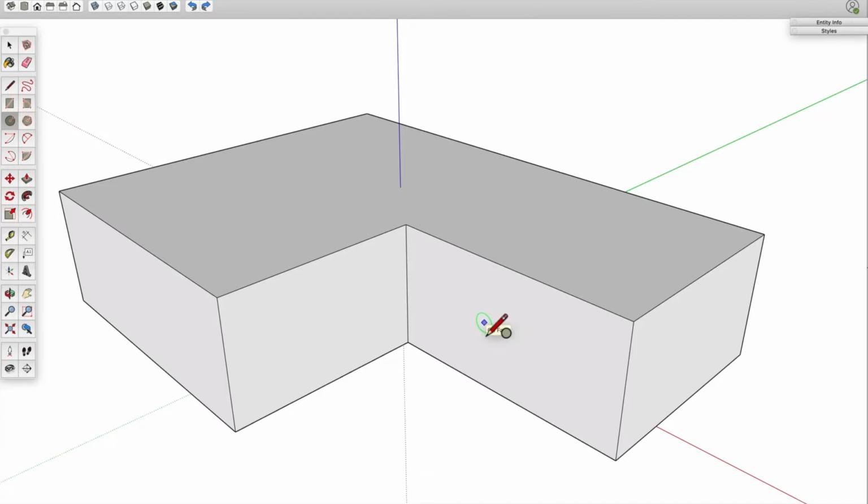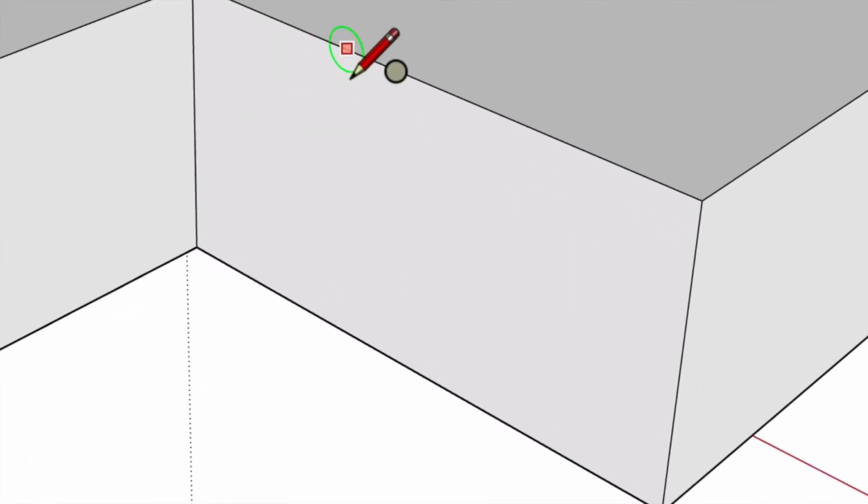Now before we start drawing, let's say we want this circle to be perfectly centered within this bigger rectangle. So to do that, we're going to need to use our inferences. Go ahead and hover over the top edge. Don't worry which direction your circle flips. Mine is flipping blue right now. That's okay. We're not clicking yet. We're just hovering across the top edge. So move your cursor along till you find that blue midpoint. Don't click there. Just hover over it.